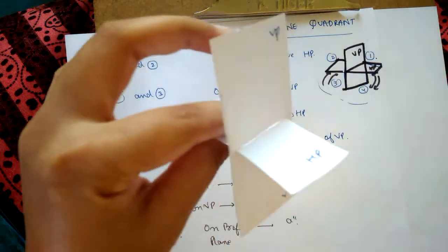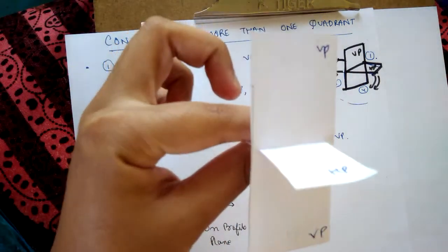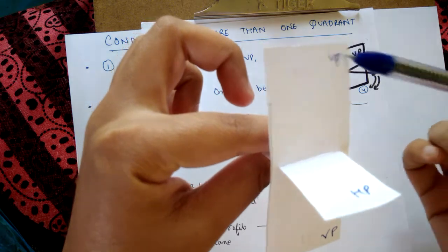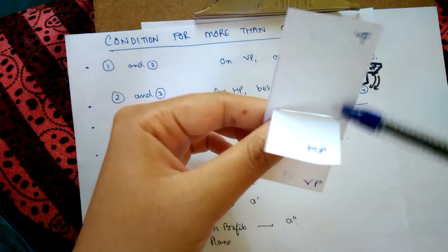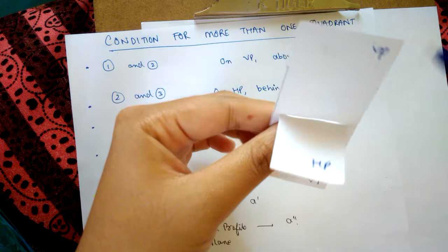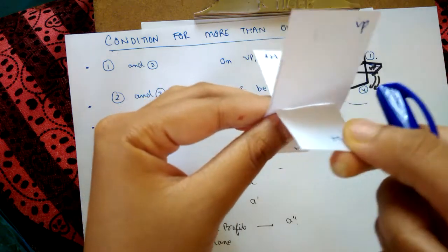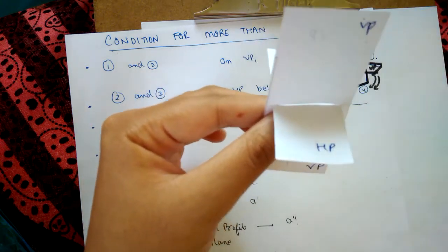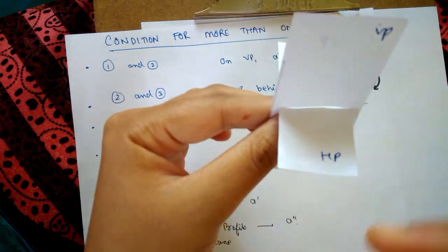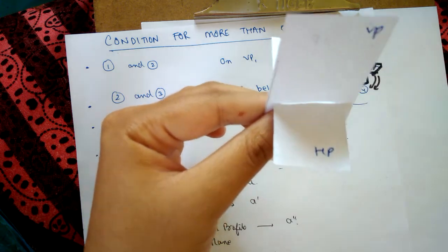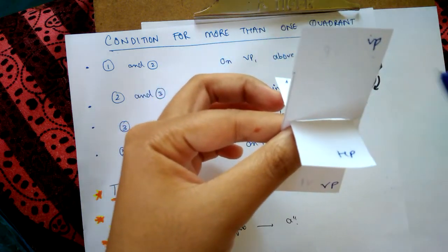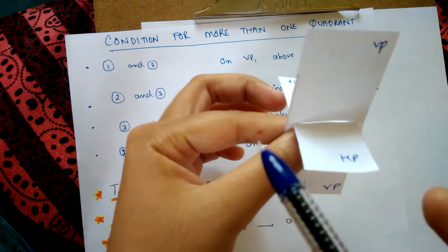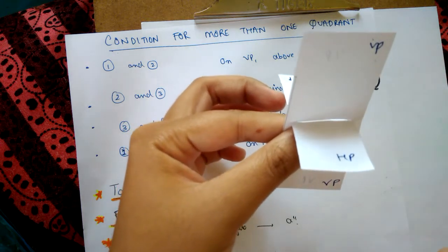Considering the first angle of projection, we have VP and HP. Now what is VP and what is HP? The vertical plane, which is always in front of us, is the VP, and the horizontal plane is the plane which is perpendicular to the vertical plane; they are mutually perpendicular. And we have to refer to the diagrams in top view, front view and side view, any side view.